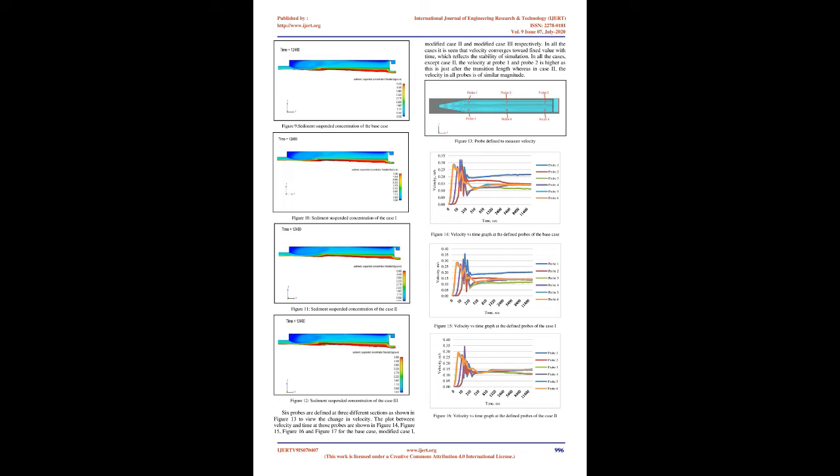The trapping efficiency for different sizes of sediment particles and sediment concentration distribution over the settling basin with respect to time is computed. The result shows that sediment concentration level is greater at entry and goes decreasing downstream. Similarly, sediment concentration level is greater at the bottom level and goes decreasing on the upper level. This is due to the sediment settling phenomena and decrease in velocity of flow.